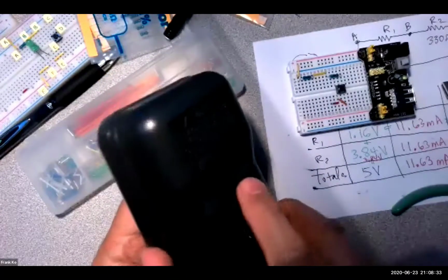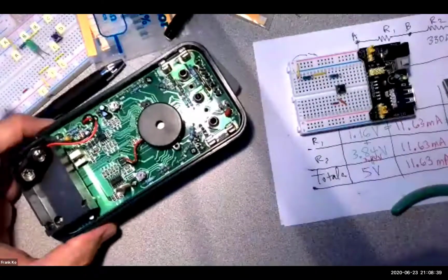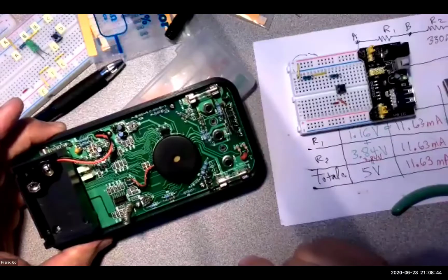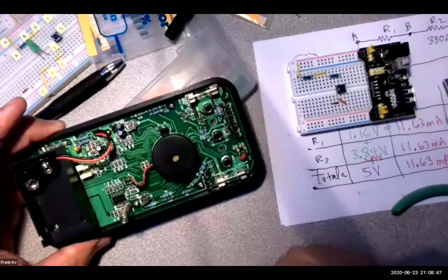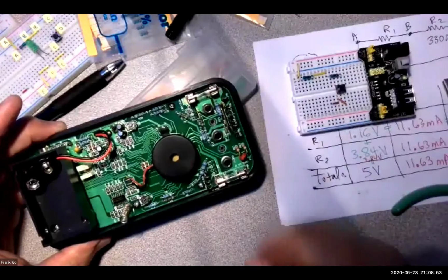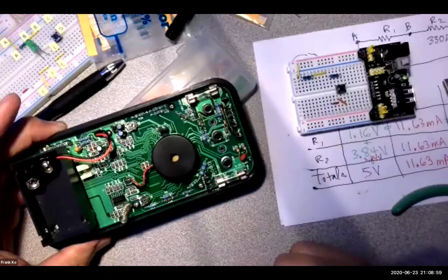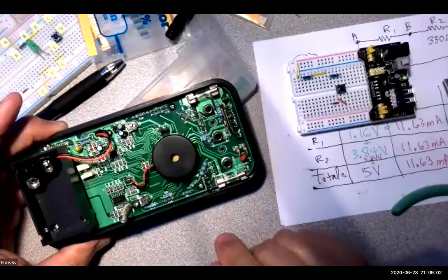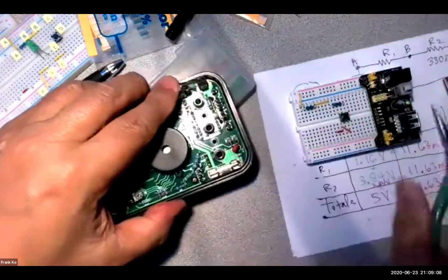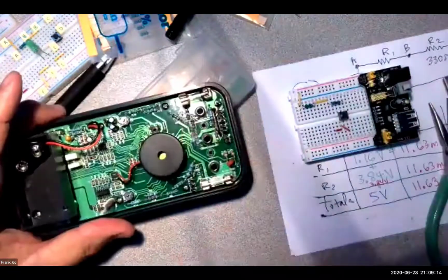And the fuse in your digital multimeter, should you ever need to replace it, here's one that's opened up. There are two fuses in a digital multimeter, one of them a main fuse and one of them a current meter fuse. If you burn out the current meter fuse because you didn't follow my directions, replacing that fuse is not hard. The fuse is maybe a 25-cent fuse. Replacing it is as easy as using a tool, lifting up one end, pulling it out, and putting the new one in like so. Did that take a whole lot of effort?